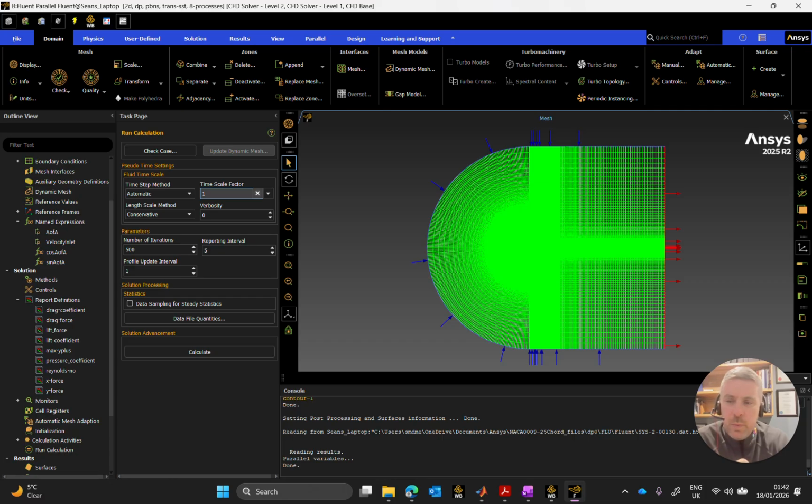I'd like to bring some of that into Fluent, maybe take a step or two out of MATLAB or Excel, do that in Fluent. Maybe we can create a CSV file and export the whole lot into MATLAB and automate that in a function to give me a final answer. But to do that, I'd need to have reportable data. And for that, I need a report definition. So for that reason, I've moved a lot of these into the report definitions. All right? I didn't have to move much of them, but I did.